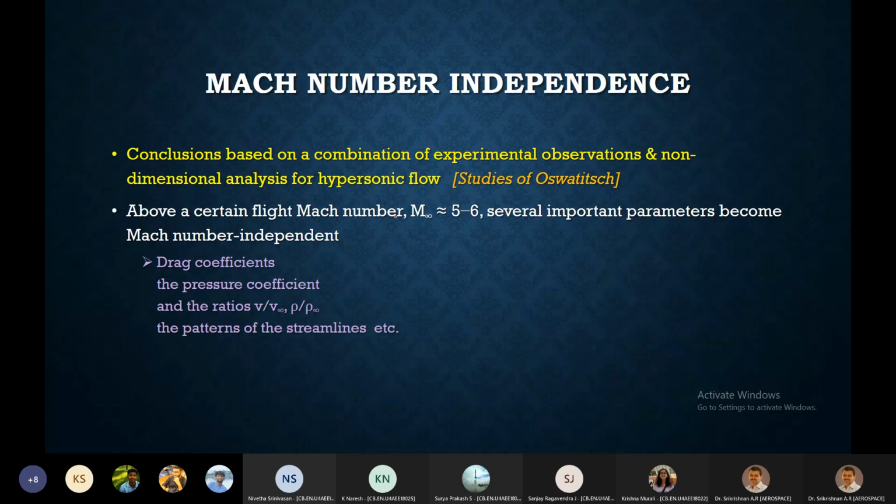No, you still lose a lot of accuracy, because when we approximate the hypersonic limit, we are assuming the Mach number to be infinity, which is not the case. So there is a finite compromise on accuracy, but for initial estimation, it's safe to consider that many of these aerodynamic coefficients are independent of Mach number.